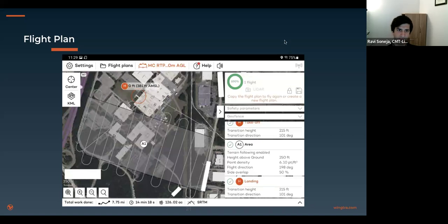The resulting points per square meter, so nominal in a single swath, was about 86 points per square meter, and then aggregate, all the swaths combined throughout the project AOI was about 116 points per square meter. This site was completed for the LiDAR acquisition in about 15 minutes, and that included the dynamic IMU calibration at the start and finish of the flight.